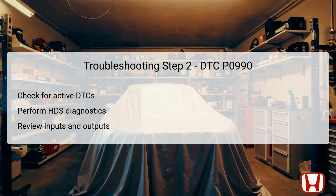This analysis also allows you to catch any related faults that could be concurrently affecting performance. If other DTCs are present, especially those concerning the transmission or PCM, it's imperative to address those issues as well. The responsibility lies in ensuring that no other active faults are obscuring the diagnosis of the pressure switch circuit. An efficient review using HDS can significantly narrow down the potential system faults.